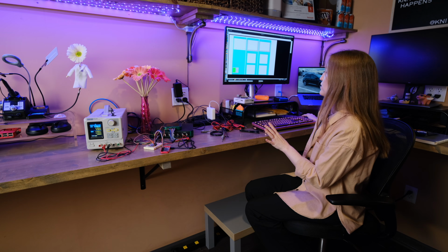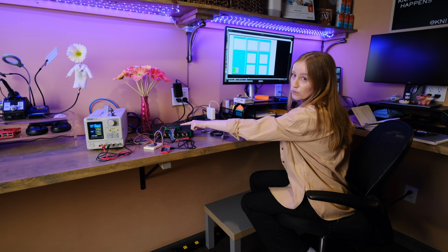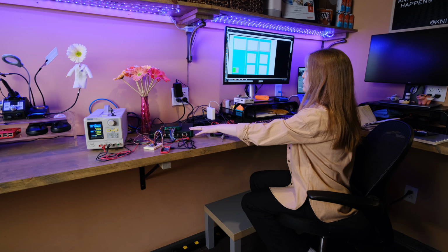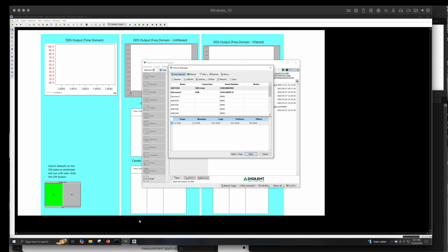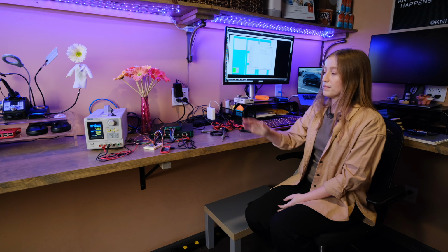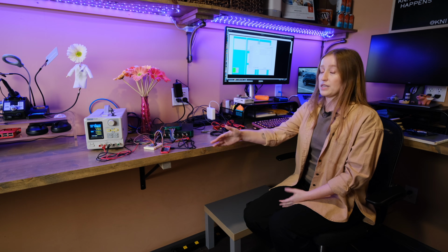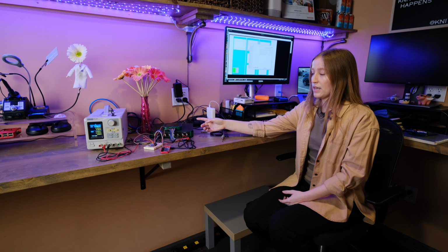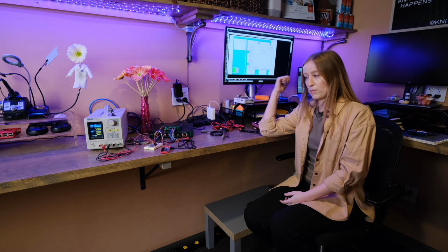The other thing I have separately is, while the Analog Discovery 3 is being controlled within DAISY Lab, I do have my ADP 3450 with the logic analyzer function. That's running separate in WaveForms. Not that DAISY Lab can't handle driving both at the same time. It's just for the same reason that I'm running the Raspberry Pi manually, because I want to control how often I'm changing the DDS output frequency. Because this is measuring the digital interface, this also needs to be manual in step with that.